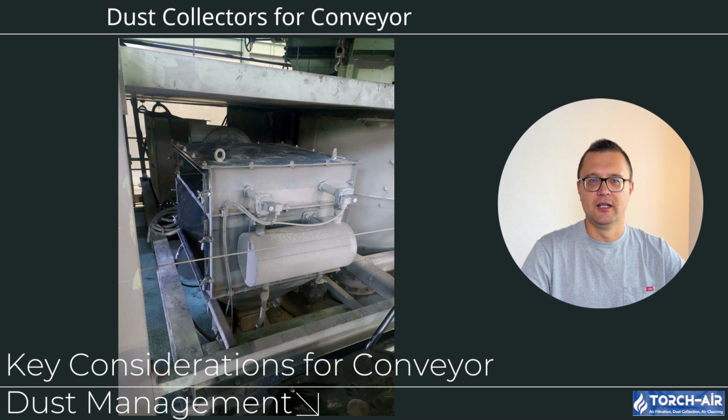C. Dust characteristics. Understanding the type of dust you're dealing with is crucial. Fine dust from materials like cement or grain requires different handling than coarser dust from sand or gravel. Your dust control system should be tailored to the specific characteristics of your material to achieve optimal results.